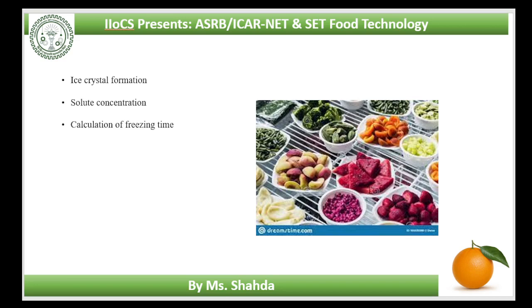It is difficult to define the freezing time precisely, but two approaches are taken. The effective freezing time measures the time that the food spends in a freezer and is used to calculate the throughput of a manufacturing process. Whereas the nominal freezing time can be used as an indicator of product damage as it takes no account of the initial conditions or the different rates of cooling at different points on the surface of the food.